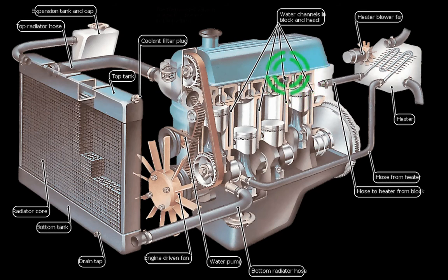Also remember that the combustion chamber, like I told you, is actually in the head, and the exhaust is constantly coming out of your exhaust valve. So all those parts also need cooling, otherwise they're going to bend or get distorted and stuff like that. You have to provide cooling to all those things to maintain that temperature. So it's going to follow all that, or I think it goes before this heater, I don't know exactly, and after that it goes back to your radiator, right?